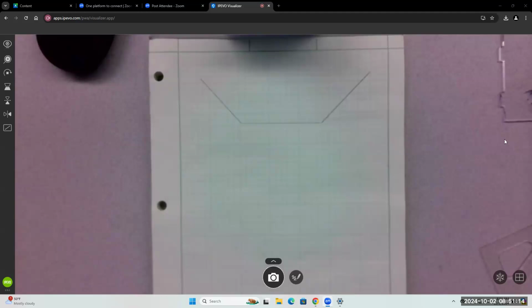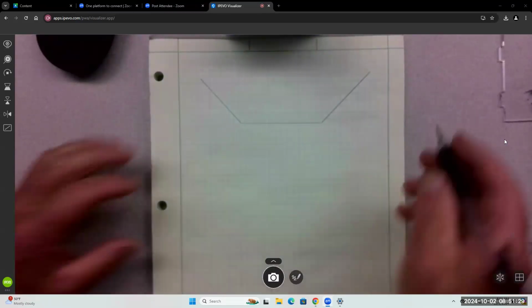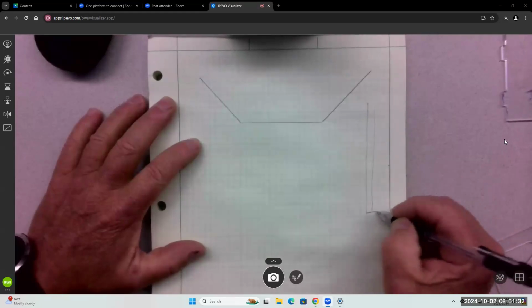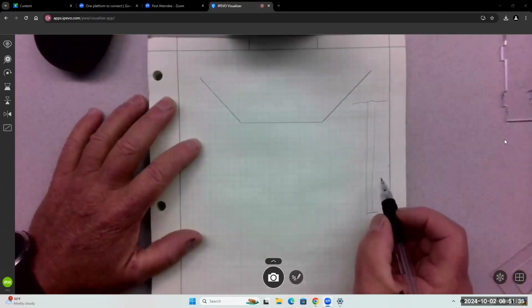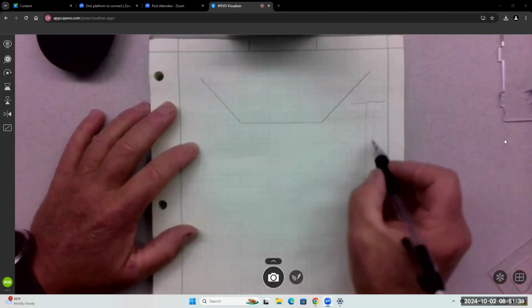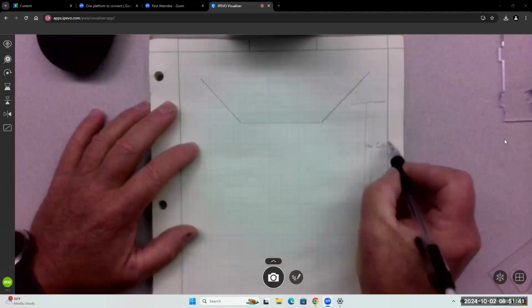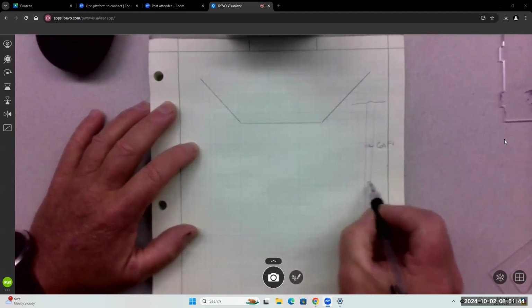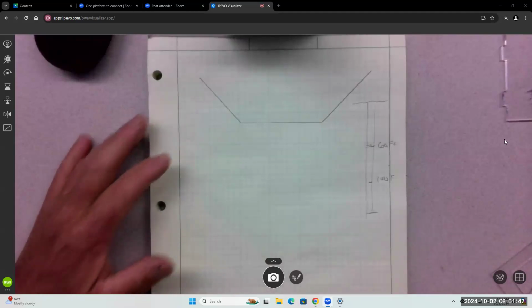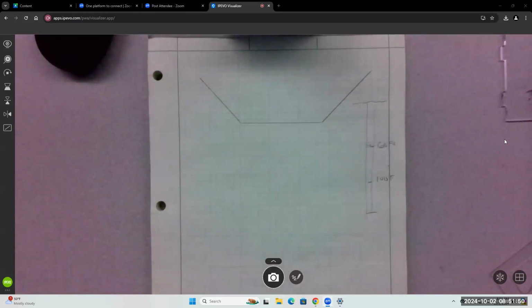Right now, I have a well in Prineville. I dug it. It's 140 feet deep. Static water level in the winter is 60 feet. So static water level is like, here's the well. Can you see this? When they popped it, in the winter, static water level is about here at 60 feet. In the summer, it's about here at 100 feet. So that's the change in the aquifer. The static water level tells you what the aquifer is doing. So we empty it all summer long, and then in the winter with the snows and the rains, it fills back up.